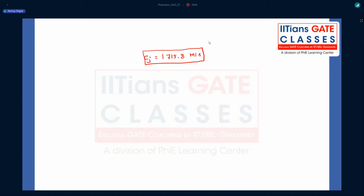So we can also approach it in another, slightly shorter way, but again that way comes from this basic understanding of our fluid dynamics and thermodynamics. So we are applying it in the right way. I know what Me is, right? Me is already known, that is 2.8. So what is Cj? Cj can be written as Me times square root of gamma R Te.